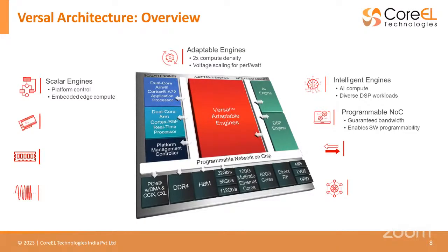So earlier we used to have everything in one place. Now we are trying to split everything into separate modules, what we're calling engines. Why do we do that, why is it necessary, and how does it help us? To understand that, when we are working with the 7 series architecture or UltraScale architecture, we also had these divisions, right? But these divisions were based on the regions, the area of the FPGA, or the area on the chip that we are trying to use, right?